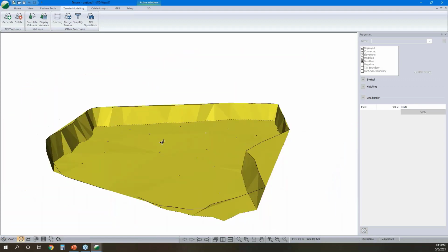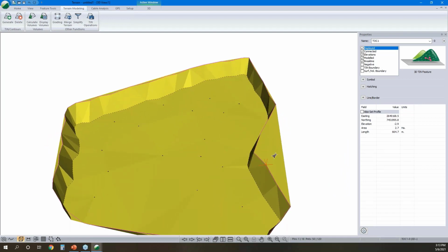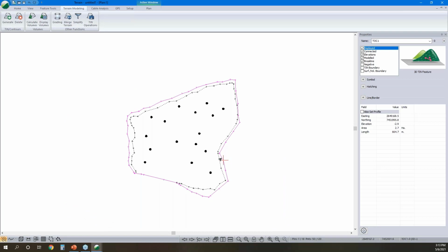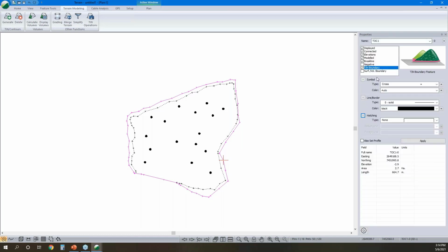And there we are. Now here, I don't care to calculate that. That's a bad triangle in that case, so I can just set this property to be a boundary feature. So, pin boundary, also change our line work, everything that we have over here. Up until now, I've been using the hotkeys on my keyboard to open up the same options.